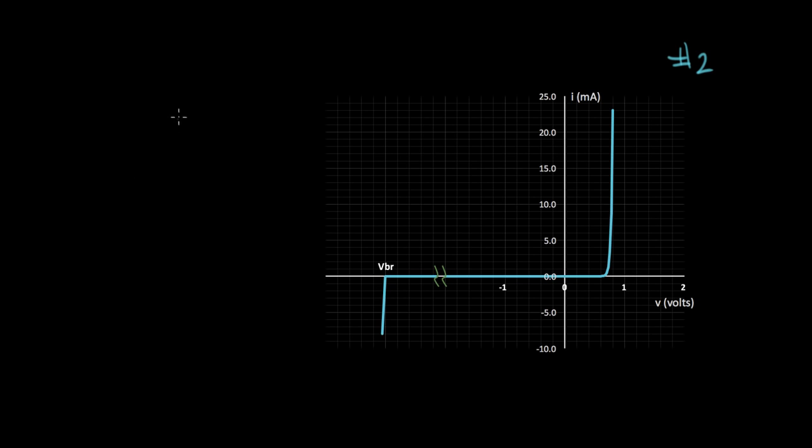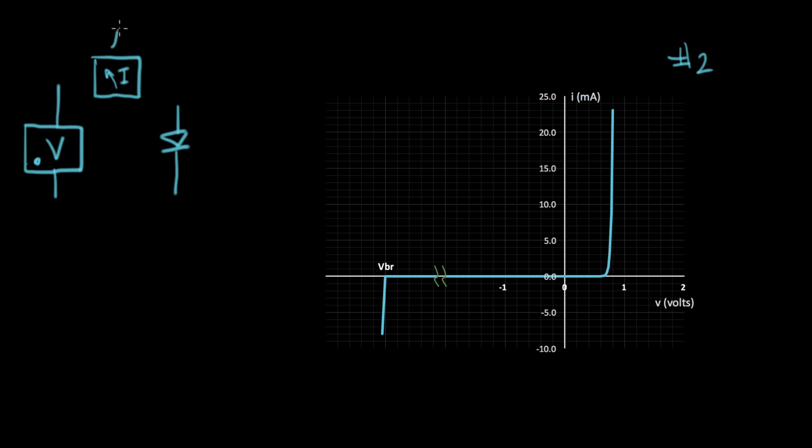So when you have a diode, if I gave you a diode like this, and I said, what's the IV curve of it? What I would do is find some sort of box that made voltage for me, a power supply with an adjustment on it, and then I would also have something that read current. So this is an ammeter, and this is a voltage supply. And we hook that up like that. What we're going to do is generate this IV curve by making actual measurements of I and V.